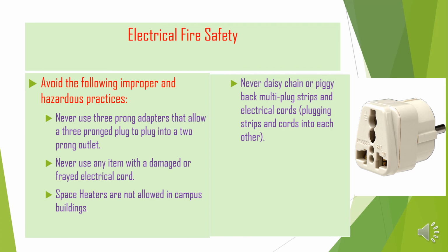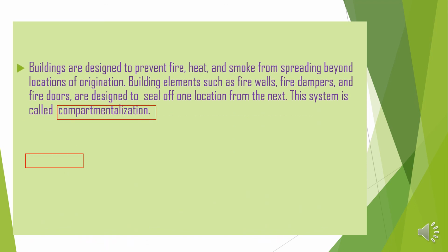Never daisy-chain or piggyback multi-plug strips and electrical cords, plug strips and cords into each other. A common source of fire again.